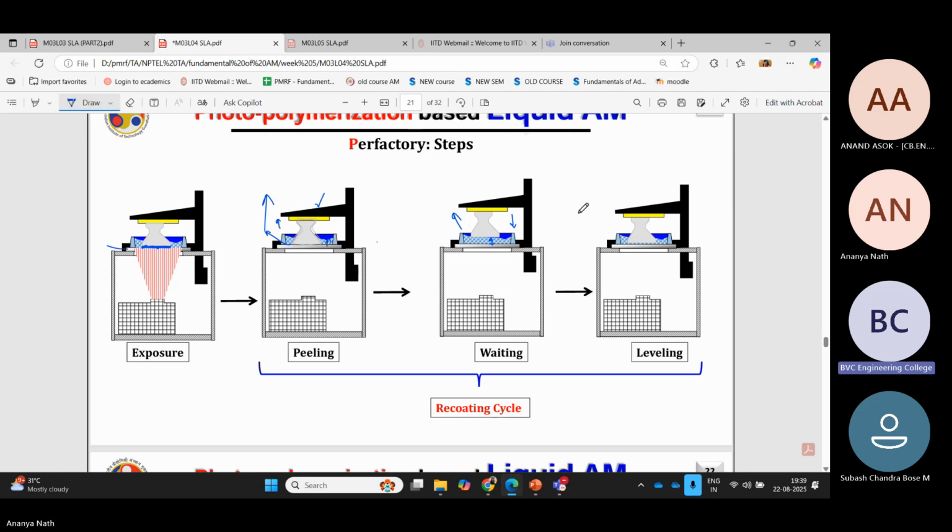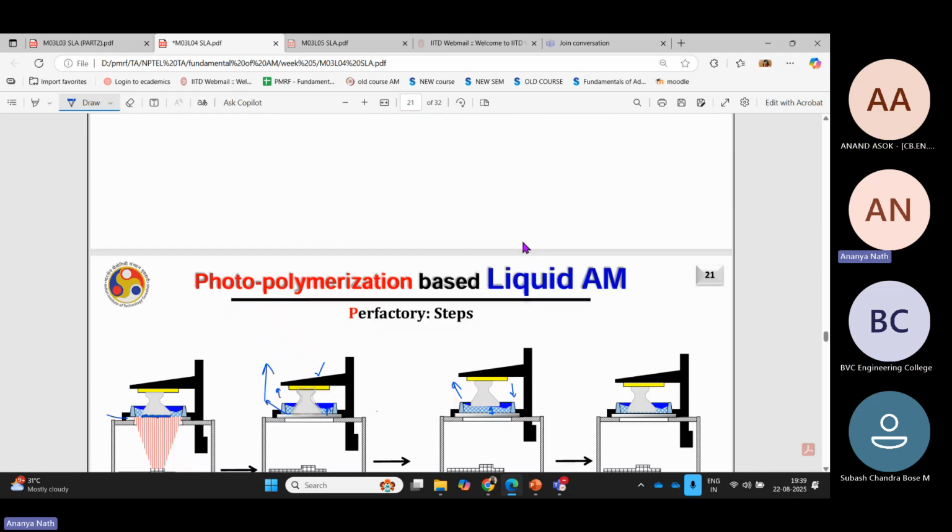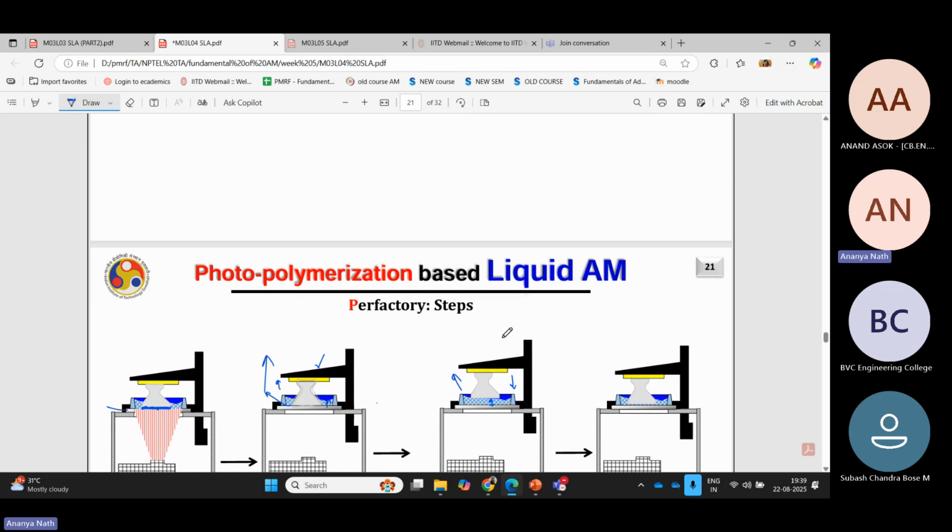And I think this method doesn't require much resin, no? No, comparatively, this process will not require that much resin, whereas in the case of deep dipping you require a lot of resin, because from the top, every time, the last layer should be dipped. Here, because of gravity, the resin is always present at the bottom only. So this is the process by which you can actually make a part which is hollow from inside, because